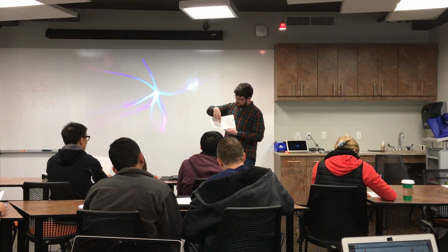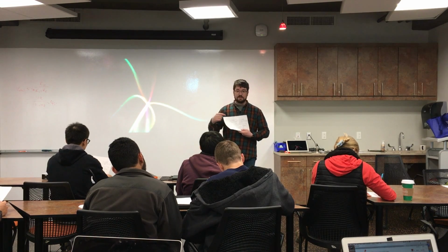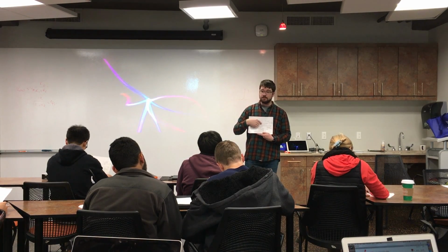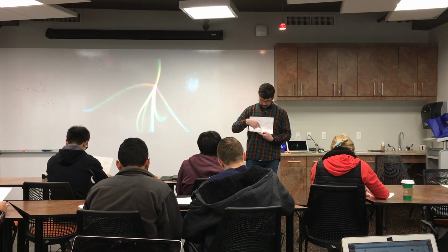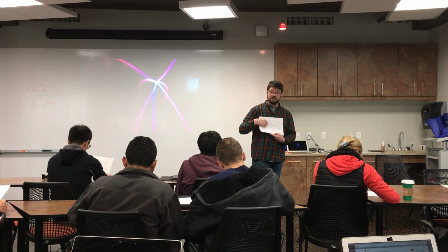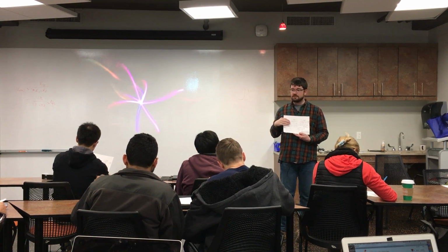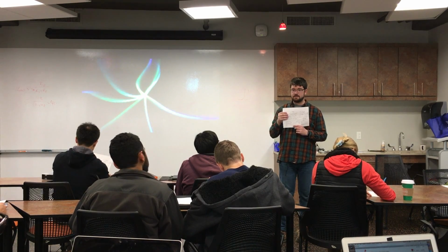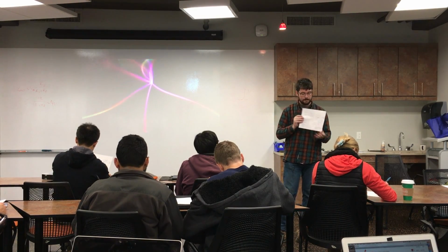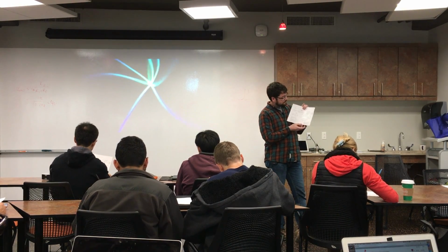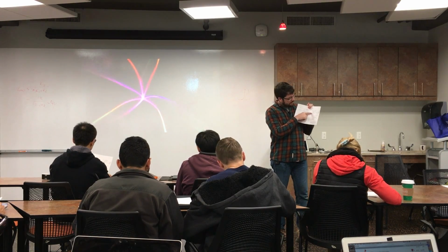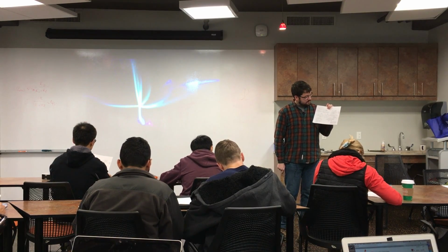That goes in with the buffered signal into this amplifier, which once again is set to unity gain. So that just offsets the signal. We have a single-ended input here, single-ended input here. That's how you zero the transducers on the biax if you've ever used it. But we're just offsetting the signal. Then that offset signal now goes into this OP177.